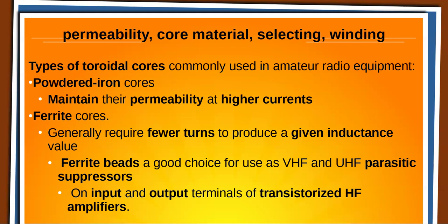In fact, you can buy an assortment from Palomar of different size clamp-on beads. I think Amazon sells Chinese versions, but you're probably better off with the Palomars. And you can put them on virtually every cable that you've got in the shack. More is better than not enough.